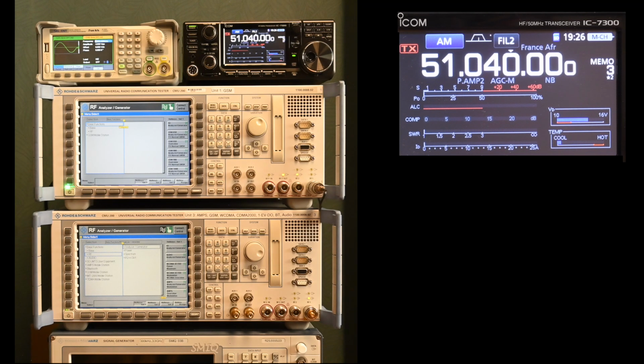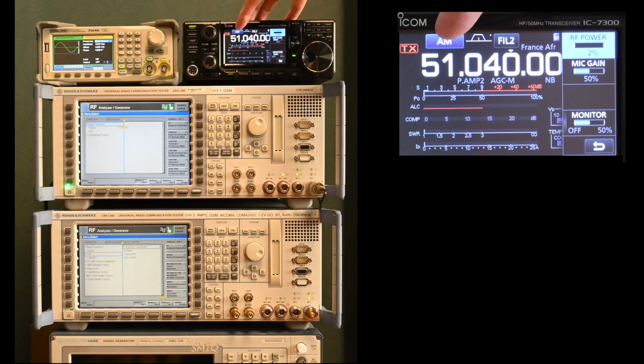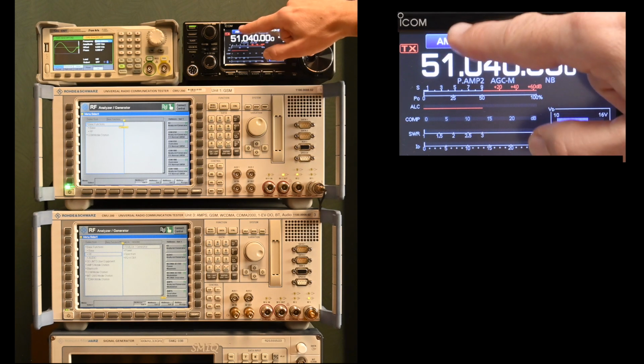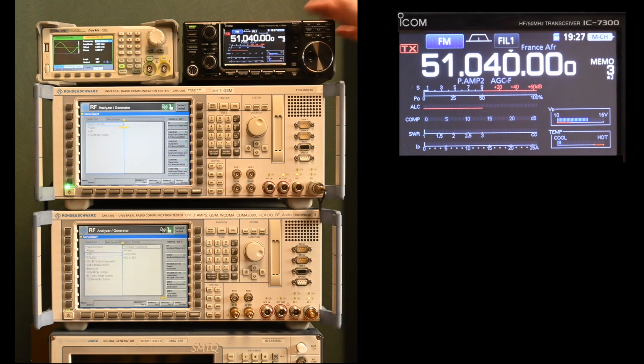So the first thing we'll do is go to the ham radio here, and because we don't want to run the full 100 watts, that would be too much, we can set the RF power to a lower level. I'll start here with 2%, which should be roughly 2 watts, and we'll be measuring what it is going to be exactly. Secondly, right now it's set on amplitude modulation, but then the actual output power will depend on the amplitude of the audio signal. So we'll go here to an FM signal, so we have a constant carrier once we turn on the transmit of this unit.